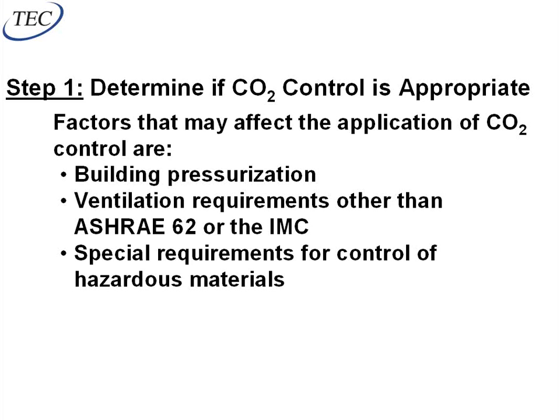There's things I have to think about, too, in addition to how many people are going to be there and how much activity level they're going to be doing. But building pressurization comes into play here. If I start modulating all these outside air dampers back, I don't want to modulate the outside air back to be less than my exhaust systems are taking out of the building, because then I'll be in a negative on the building, and then I'll be sucking doors in and things like that.